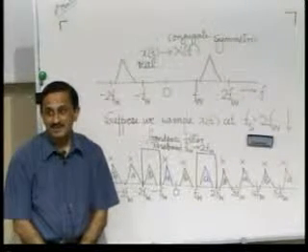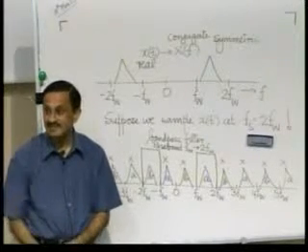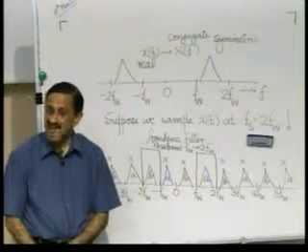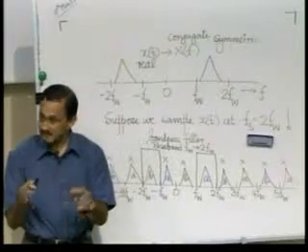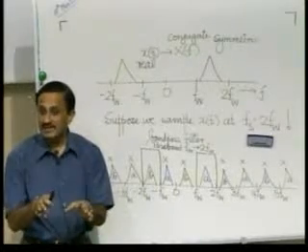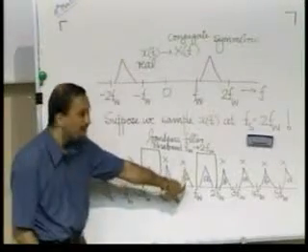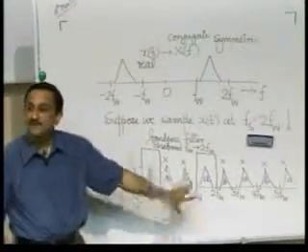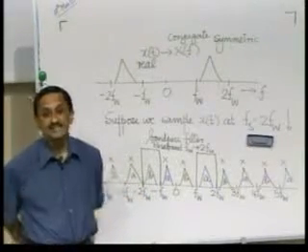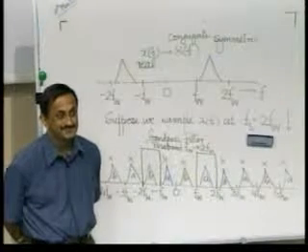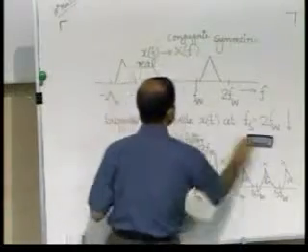So, this is an example of the converse situation to what I discussed earlier. You see, you can allow aliasing to occur or aliased versions of the spectrum to fall in an unoccupied band. That is the idea being used here. This is an unoccupied band. So, you do not mind if aliased versions fall there, because you can filter them out afterwards if you know the original band is unoccupied. Now, this is an example of what is called band pass sampling.